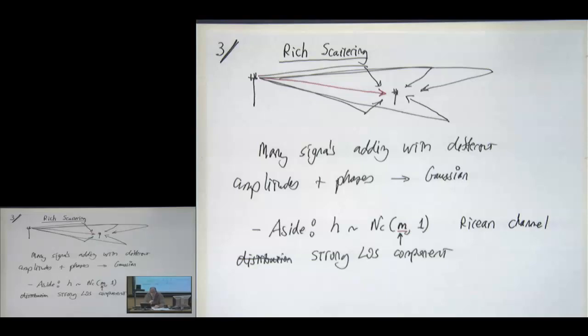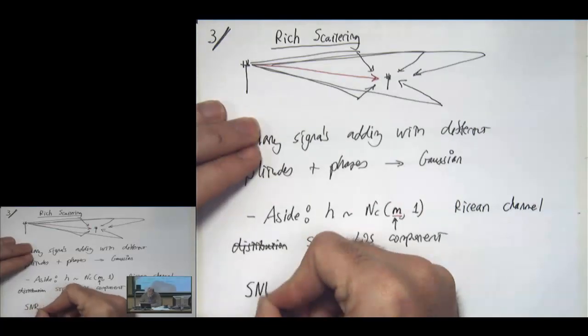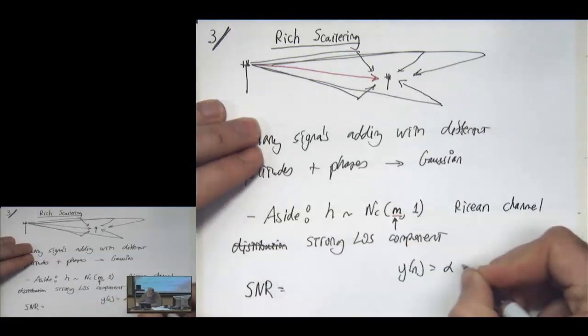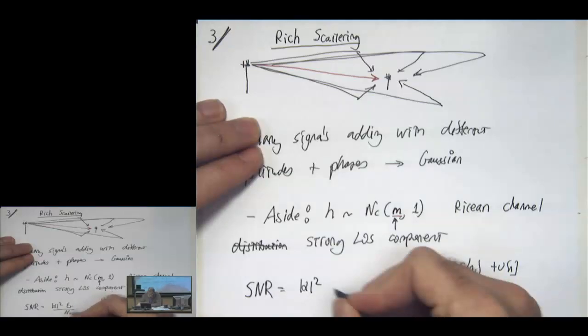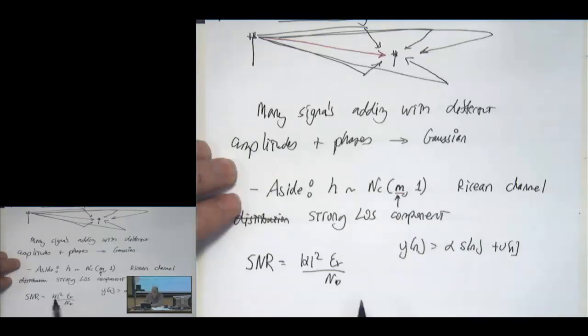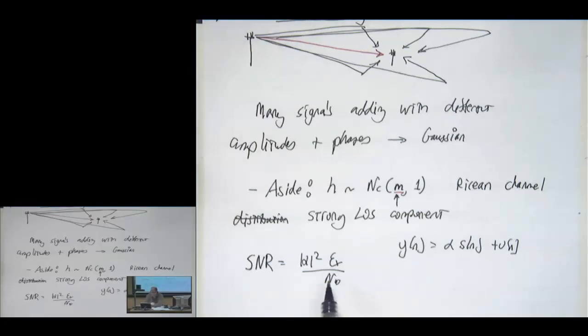Why is the envelope, or? Yeah. Okay, so we'll see that in a second here, but essentially, if you remember, when we derived the SNR for a system where we had something like this, y of n equals alpha s of n plus v of n, we derived the SNR of that when we were looking at the maximum likelihood detection. We found that the SNR was something like this here. So the system performance was fully determined by the magnitude squared of that alpha. So the magnitude is the envelope. Magnitude squared is the power. So that's maybe the main reason.